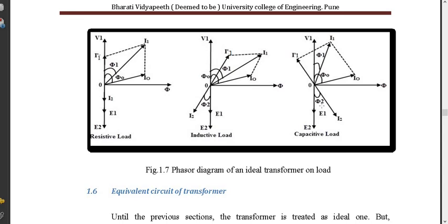So normally, instead of having this dispute, the transformer is rated in kVA and not in kW. This is one of the reasons why it is rated in kVA and not in kW, since there are three different power factors in the transformer.